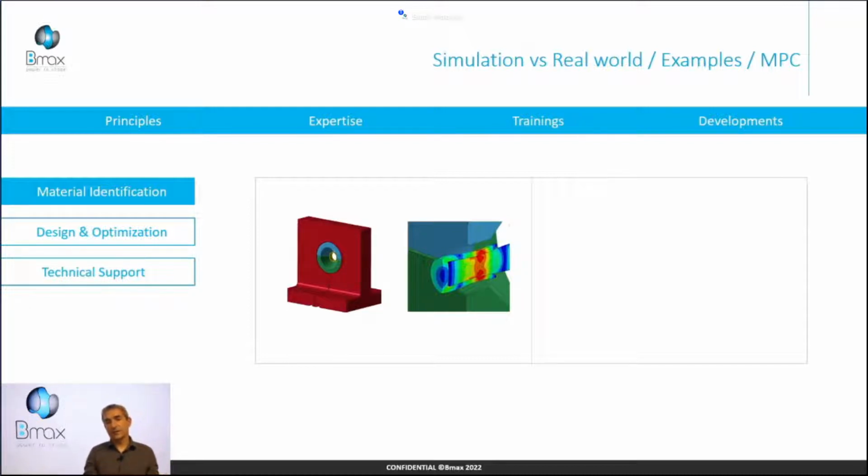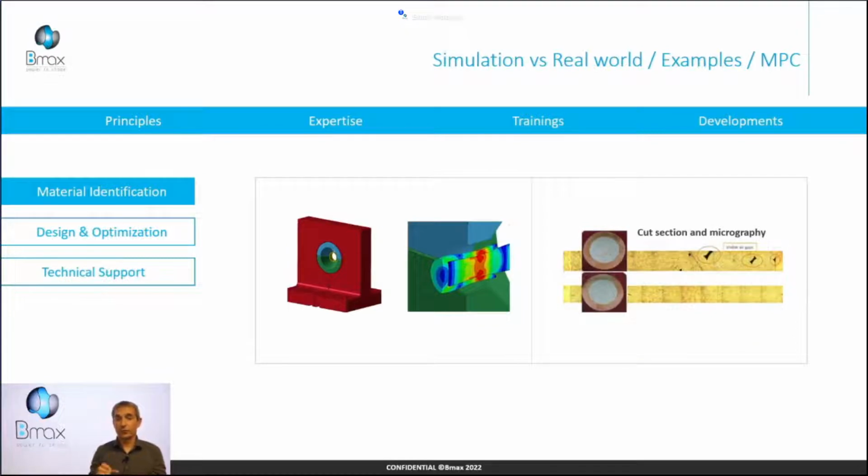When we apply this setting during the test campaign, we are able to remove all the clearance between wires. It's a good point to minimize the resistivity of the assembly, and the ovalization of the lug respects the requirement from the customer.